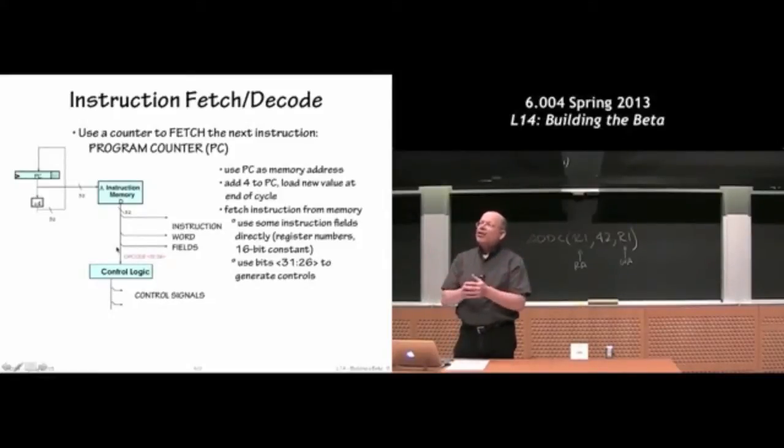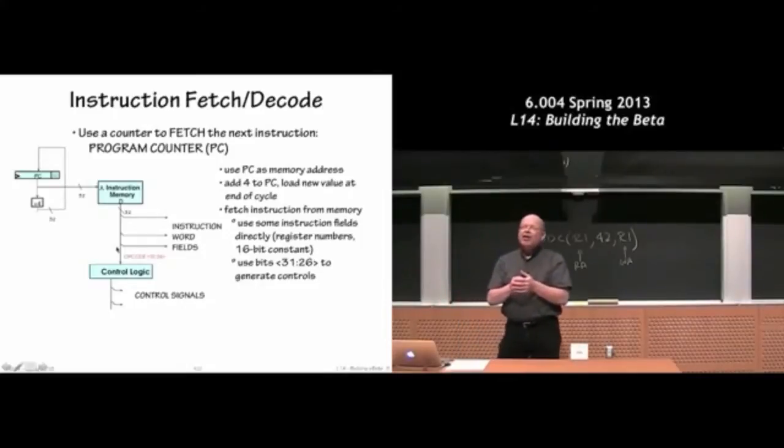We've chosen not to do that, but with a cleverer choice of encodings we could have simplified the control logic. I think you'll discover that if you implemented the control logic not as a read-only memory but as just a bunch of discrete logic, it's only a handful of logic gates, so it's not very complicated. The transformation from opcode to ALU function code is actually pretty simple.